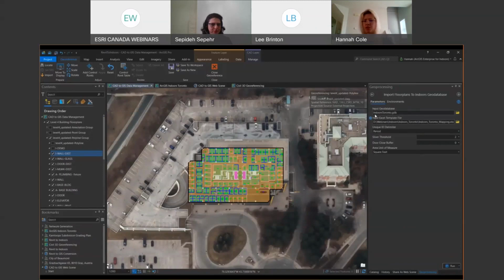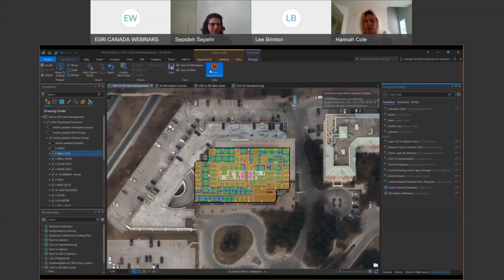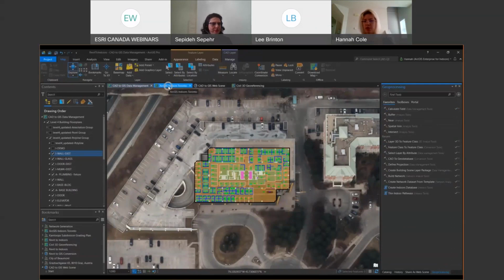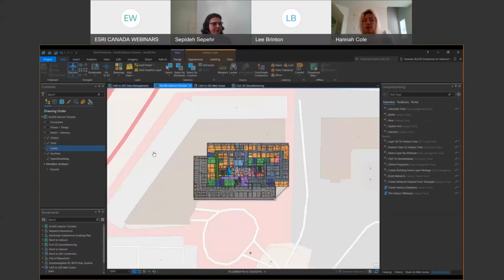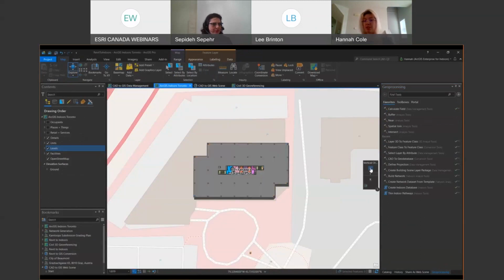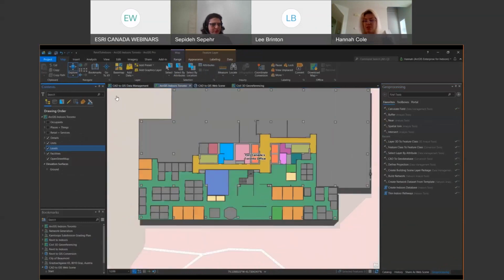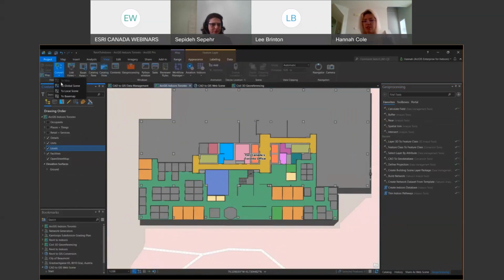In addition to being able to map in 3D, this special GIS data model is also floor aware, which means that the end user or GIS analyst can navigate up and down or between floors in the building using the map's floor picker tool, which also runs on your mobile device. The GIS is able to differentiate between floors in the building based off of elevation and vertical order information, which is contained inside this data model. The building information will now exist as facilities, levels, units or rooms, and details layers.